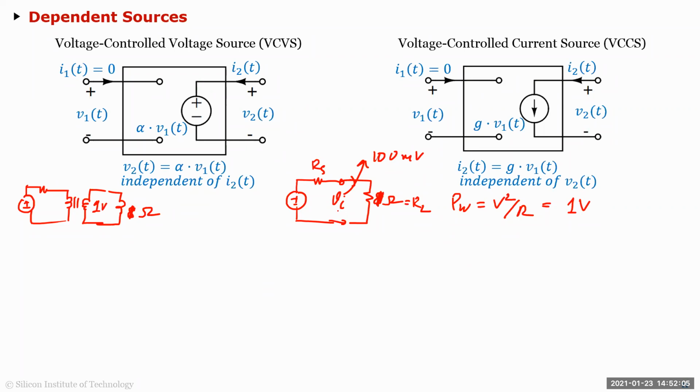Okay. So what happens? So this is 1:10 still. You'll still see the 1 ohm here, because what will happen is, to drive this, you have to drive 10 times more current here, because the impedance gets reflected by 1. So you'll see 0.1 ohms now. Because if you have a transformer 1:10, and I put a 1 ohm resistance here, when I look here, it's 0.1 ohms.